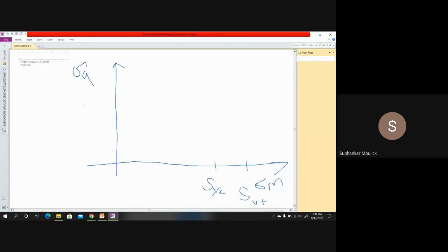Similarly, if I consider alternating stress, load is changing every time with respect to time. That means fatigue is happening. Then according to fatigue, material can fail at endurance limit SE, and material can fail at SYT if I talk about ductile material, and SYT is bigger than that of SE.